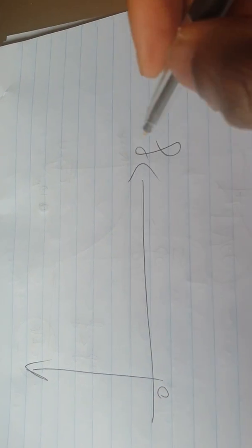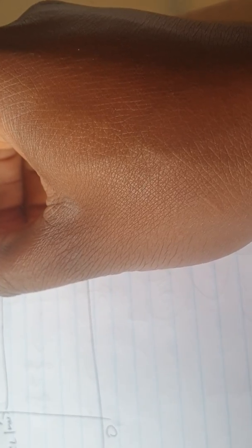If you look at the gain behavior of this specific low pass filter circuit in terms of the frequency, because we are analyzing in terms of frequency and we are looking at the closed loop gain, we're going to have the maximum closed loop gain there, and as we go along, above a certain frequency the gain will start dropping, and when it drops by what we call minus 3 decibel, we're still going to analyze that just now.